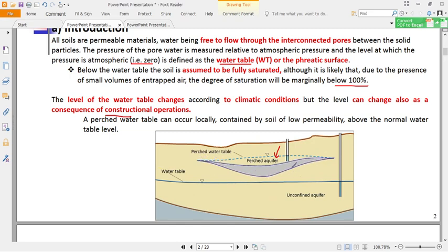The deposit of clay within a small area will be able to hold water. But you may find that the real aquifer is below that deposit. So when you dig your well, you may locate water within the perched aquifer, and during the dry season, you have seen that such wells do dry up, because you have no source of water.